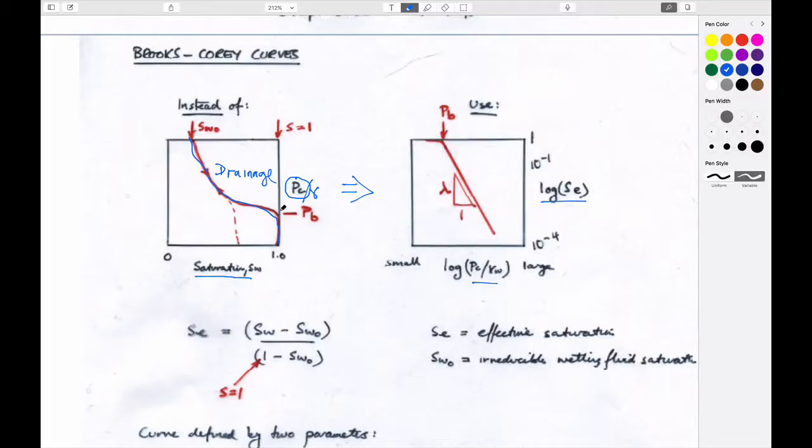It might seem like a futile idea. Why would we do that? Stupid, right? Well, we do it because we find out that if we do it, instead of having a complicated curve, we actually get a straight line with an intercept. And remember that these two figures are exactly the same, they're just plotted differently. It's divided through by unit weight, and they're plotted as log instead of natural figures.